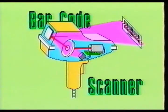The operation of the barcode device is very simple. It illuminates the barcode symbol with a narrow beam of light which rapidly moves back and forth across the pattern. The laser beam will scan at a rate of 40 scans per second or more. As the beam strikes the dark bars and the white spaces, it reflects back into the window of the device, bounces off the oscillating mirror into the larger lens, and is then focused back into a narrower beam to be detected by the photodetector. The photodetector then converts these variations of the reflected beam into a series of digital pulses, which is then fed into the computer for further processing.